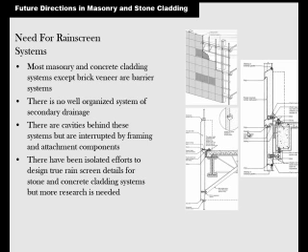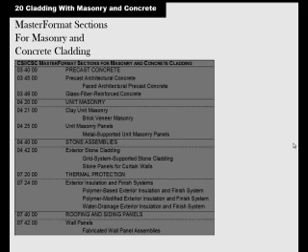And you can see here on this stone one, they've got the drip edge and they've got the labyrinth, and hopefully there's some sort of sealant that comes down like that. So, they're doing their best, but you want to screen against the rain. Cladding is found in these sections of the specifications: precast concrete is in 3, and masonry is in 4. Stone is in 4, because stone and masonry are considered the same or similar. Thermal protection, which would be the insulation properties, is found in section 7.